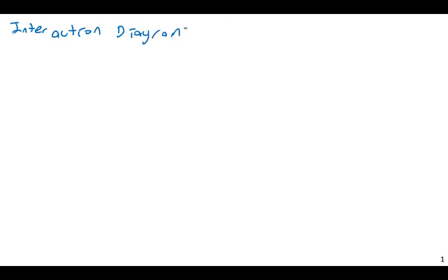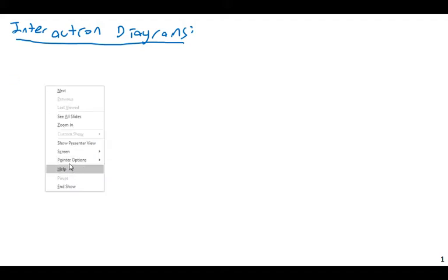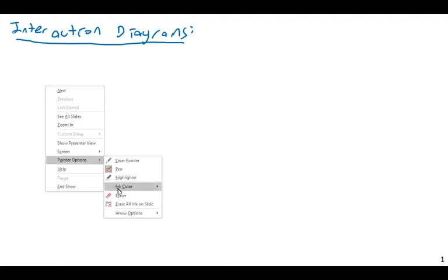As we discussed previously, in almost all cases, concrete columns are going to experience some level of moment. This is really because of their monolithic construction. When I say monolithic, I mean two things. One, they have larger dimensions, which means you're more likely to get eccentric loadings, and also they are cast together with their beams in most cases. They're locked together with their beams and floor slabs, so it's almost inevitable that your connections are going to transfer some amount of moment to your columns. Now we discussed how short column design takes that into account.